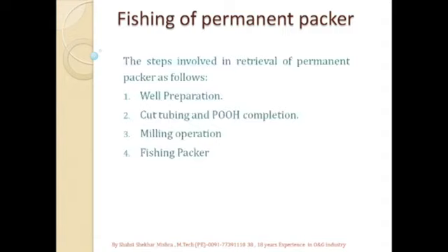So fishing of a permanent packer involves four main steps. First comes well preparation, where we deploy the rig and do the surface preparation. Then comes the cutting of the tubing and pulling out the completion, then milling of the packer slips.